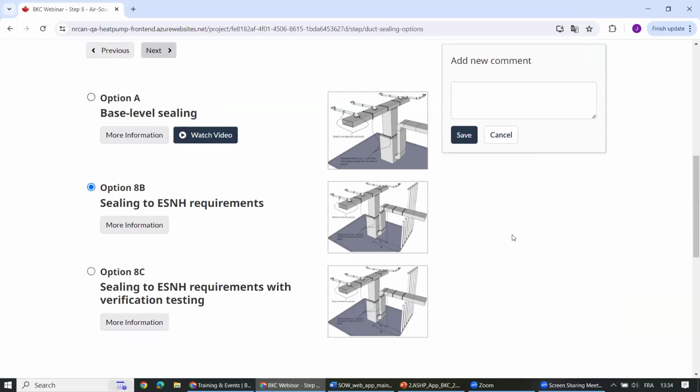Well, again, ductwork, even well-assembled ductwork, still tends to leak at each seam and transverse joint. So to ensure that the airflow is actually getting to each room without being lost to a wall cavity or to any other space in the home, we do recommend duct sealing either with tape or mastic, or even with AeroSeal in some cases, to ensure that the ducts leak as little as possible.